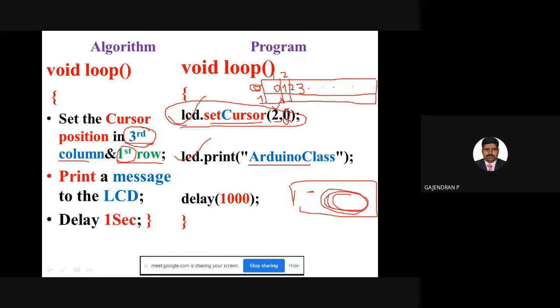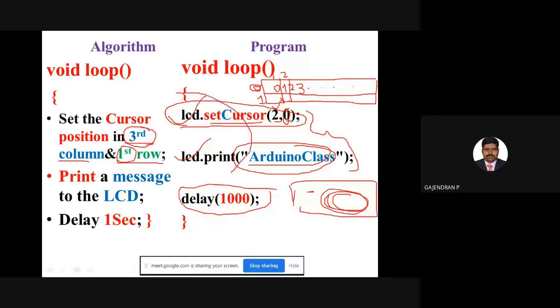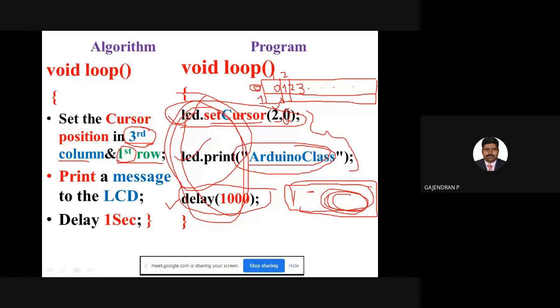Then we will send the data. This is the data we are going to print. In void loop, the function happens infinitely, so if you give the input rapidly, you won't get the exact output. For that, we give some time delay to this microcontroller to function. Then we are going to update the value from our Arduino board.